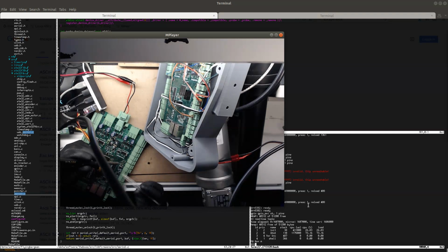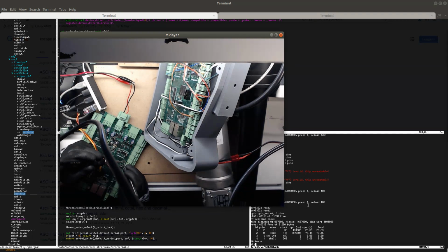And what I'm also going to do is remove the solder mask from the ground pad, which is one error that I did on the footprint. I did not uncheck solder mask from this pad that I've created. So the pad is covered with solder mask.